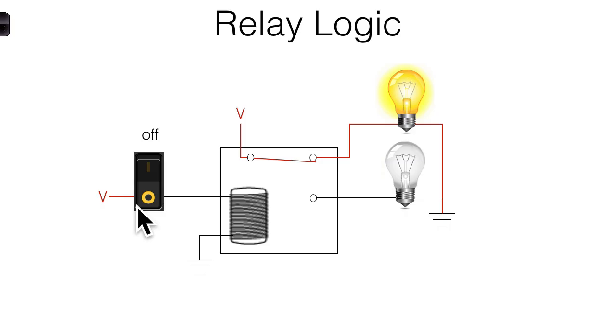Notice over here, and I'm just walking you through the basic steps, so just stick with me. Over here, we have our light switch, just like on your wall, or the power switch on your computer or your monitor. It's off. And when it's off, power is not going to flow to whatever is downstream of it. Power's coming in. You can see it's red. It gets to the switch, and it goes, oh, I can't get through there. This thing is turned off. The switch is off. I can't get through. So therefore, the coil is off. And this is the state that it would be in.